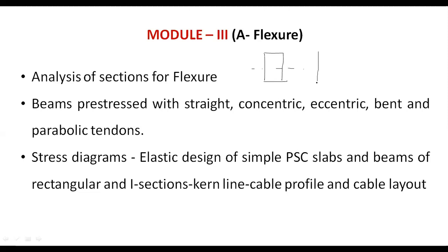So if I try to draw the pure bending, I mean the bending stress of this particular rectangular section, your stress diagram will be like this, isn't it? So at the neutral axis, your stress will be zero. I mean your bending stress will be zero. Maximum will be below the neutral axis and above the neutral axis at a distance of y by 2, right? So in that way, your member is going to have a stress diagram. So this is called a bending stress diagram, okay, or flexural stress diagram.